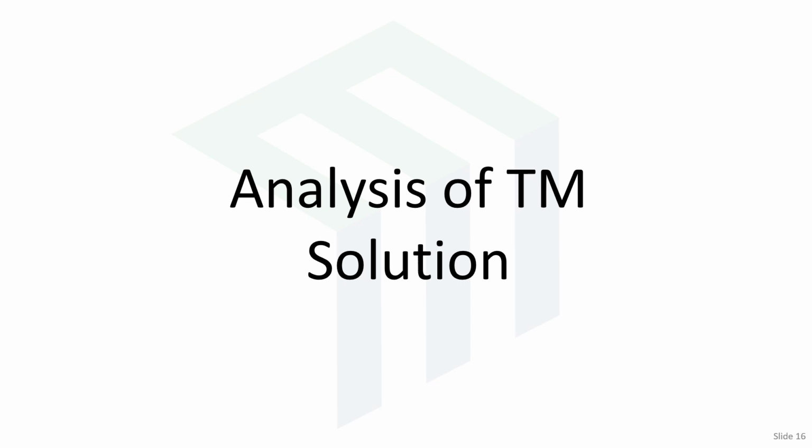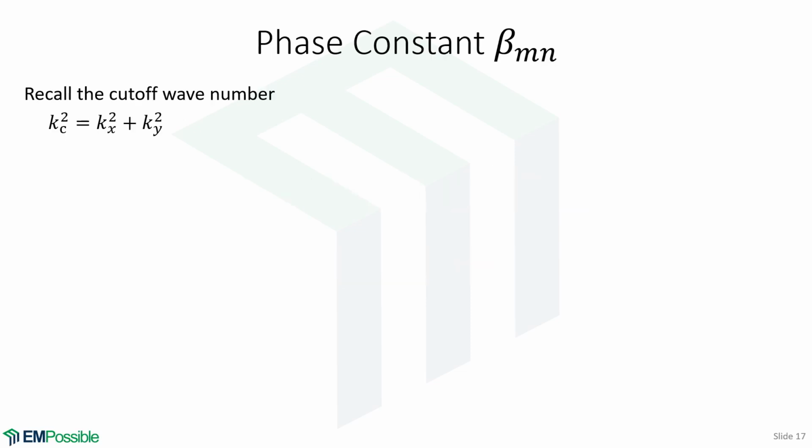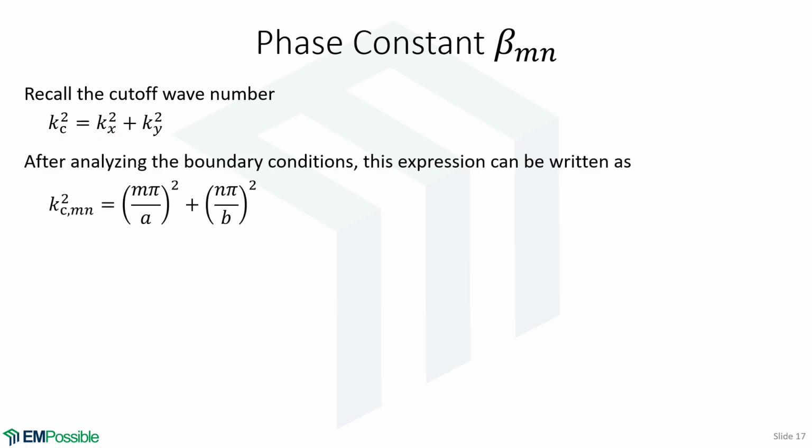Analysis of the TM solution. Let's think more about the phase constant. Remember our separation of variables, how we were required to define the cutoff wave number as the sum of kx squared plus ky squared. So we found expressions for kx and ky that enforce the boundary conditions.